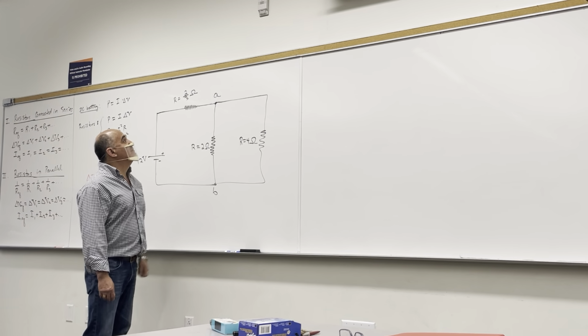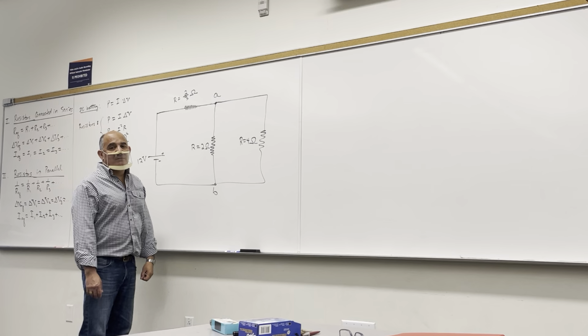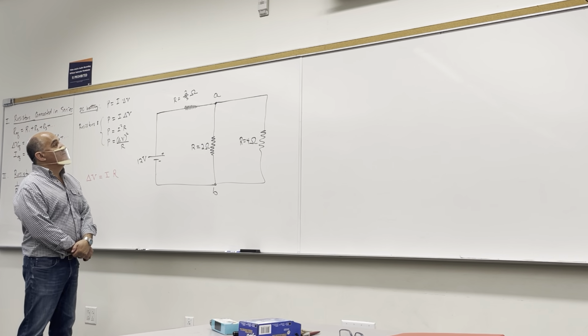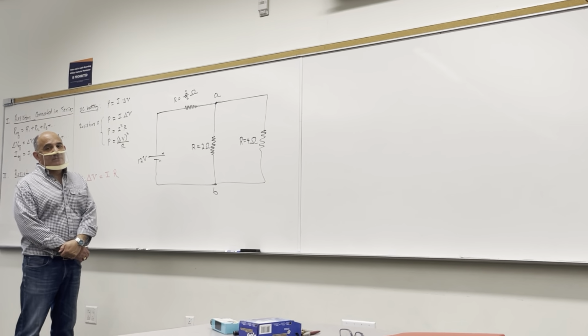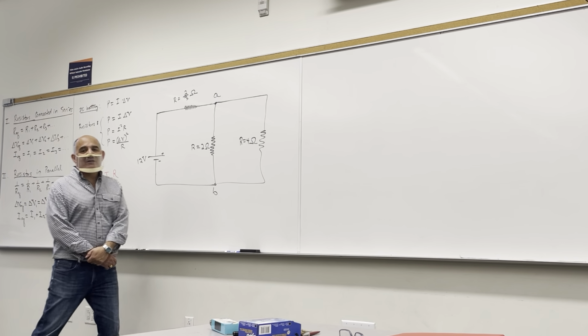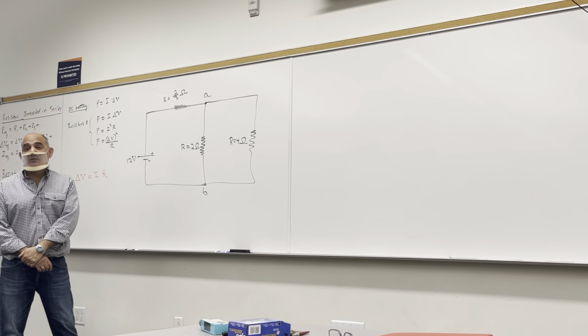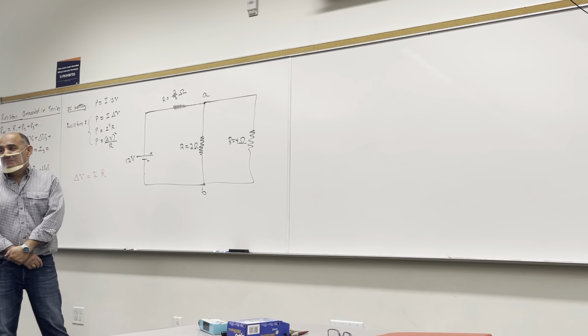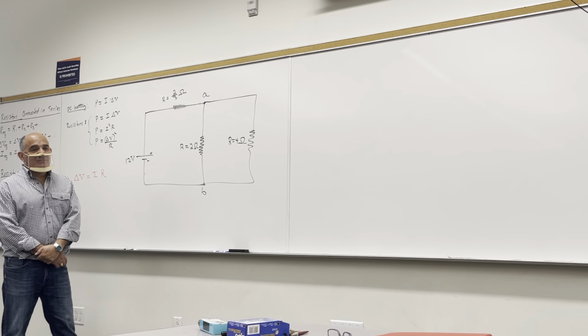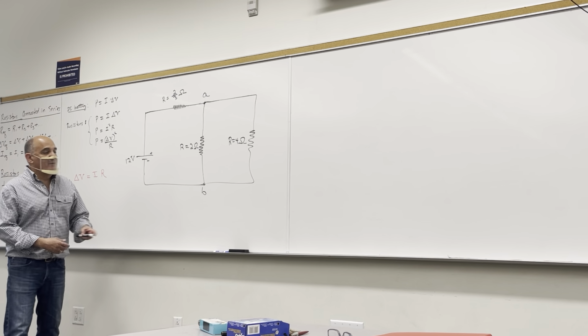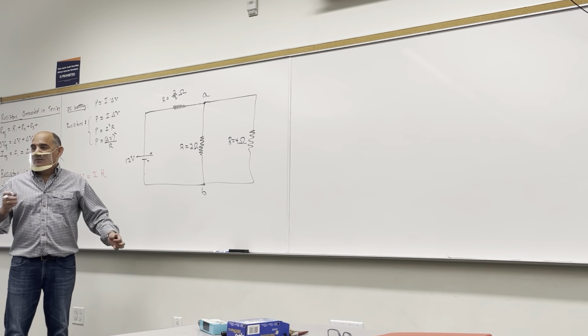And then to find everything for resistor 2/3 ohms, we could say that the top 2 are in series with that one. Does that make sense? We could condense. Okay, so let's do one at a time. Which one should we do first? I understand what you're saying, and it's correct. But let's just do one at a time. Just the in parallel ones. Okay, so which is connected in parallel to what? The 2 and 4, right?